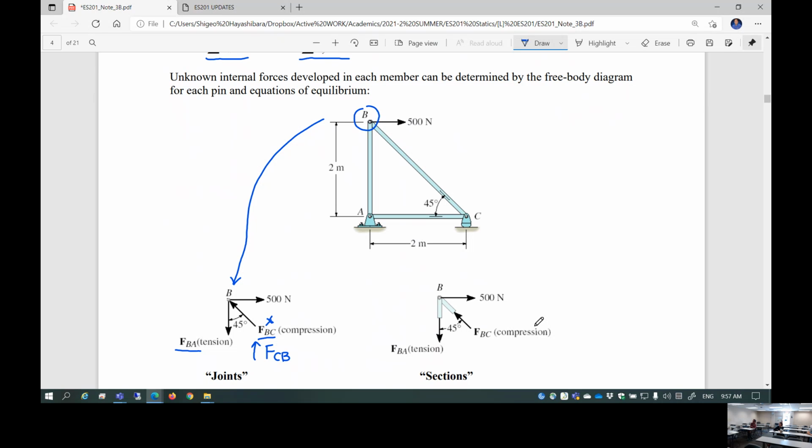Apply force in X and Y. If this is the problem, you have no problem. But suppose you are dealing with a truss with 2,000 joint points. Each location needs two equations, so that's 4,000 equations with 4,000 unknowns. It's a nightmare to do by hand. So you probably want to have a computer program to handle such a thing.